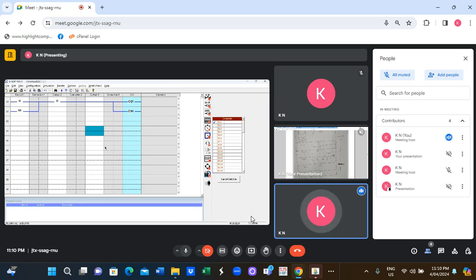So this is I1, a start switch. I2 is a stop switch, Q1 is a light, and N1 is a motor contactor coil. This N1 is a normally open contact, this is the auxiliary contact. I1 is the start switch, I2 is stop, Q1 is the lamp, and N1 is the motor's contactor coil, and the N1 here is the auxiliary contact.